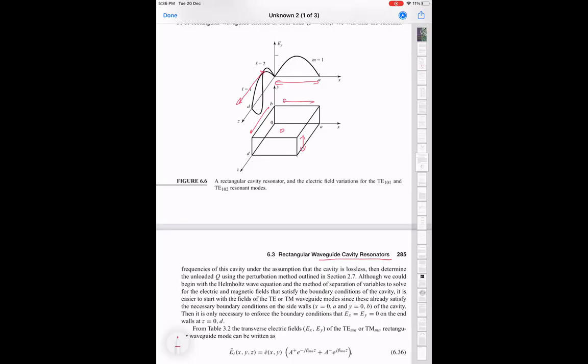Lower capacitance, just because the dielectric is essentially vacuum. So you can get different effective capacitance. So that's also how the introduction of a pin will pull the frequency, which will also change. Because the internal capacitance is very small, the external capacitance starts to have a bigger effect on how much it gets pulled.